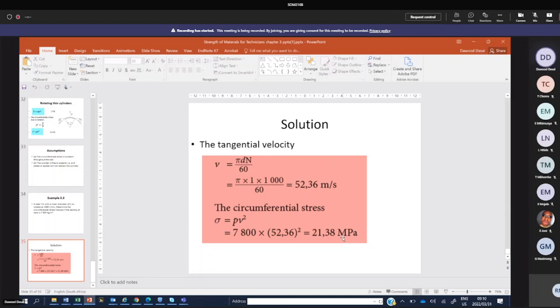The force in must be equal to force out. You write that as an equation. Or pressure in is equal to pressure out. All the same thing. Or internal stress must be equal to the stress resisted by the bolts. The internal force must be equal to the force outside, which is the force resisted by the bolts. If you have 10 bolts, the area is pi d square upon 4 multiplied by 10. Keep that in mind. Very important. Other than that, guys, it's a very easy section.